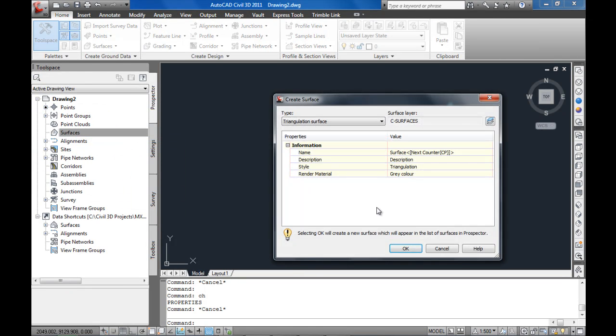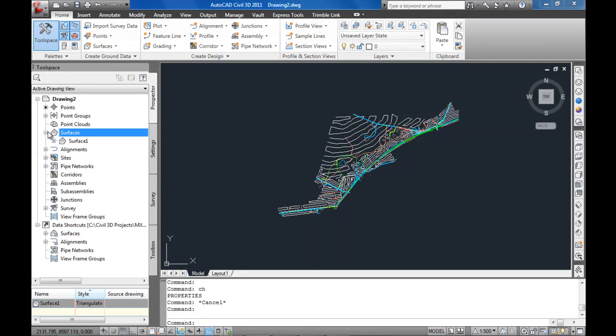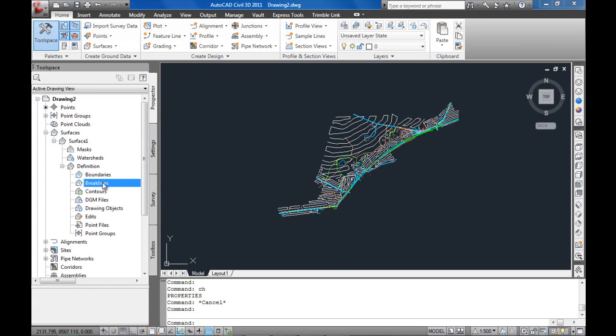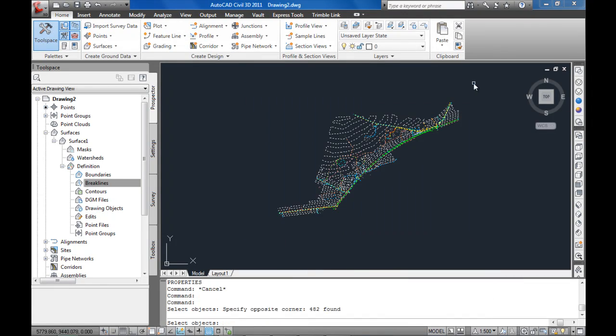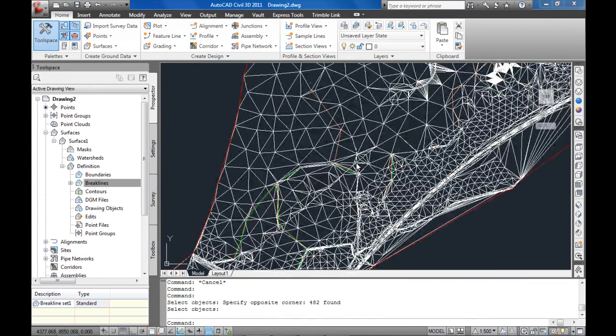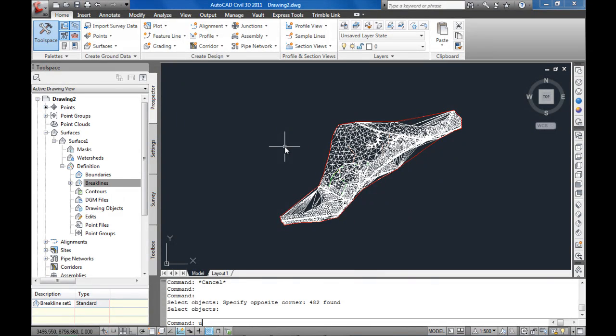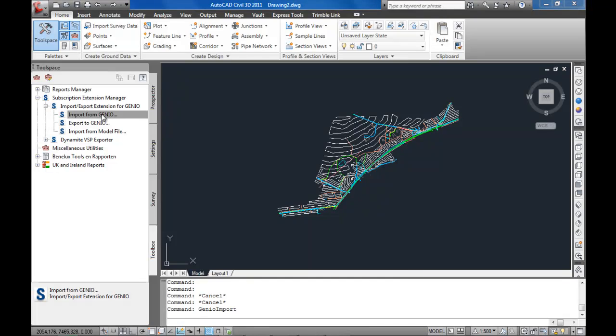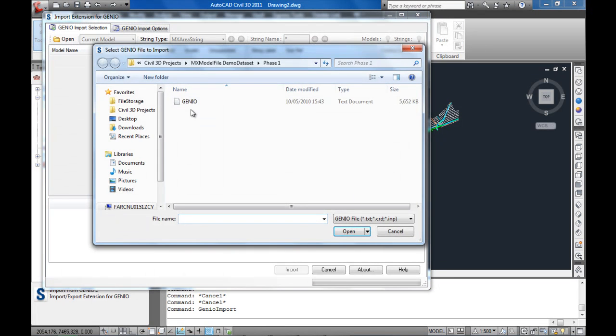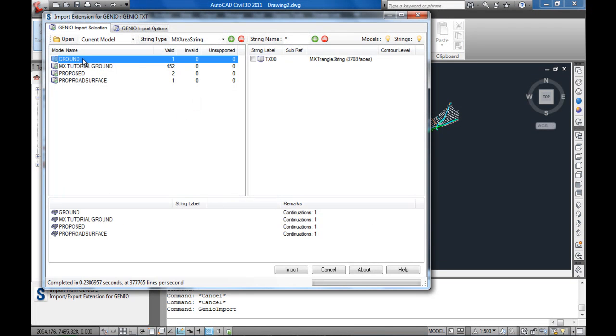Anyway, this is something now that you could create a surface from in Civil 3D, just using the typical surface creation of using break lines and COGO points if you have those within the drawing. If we step this back, we'll just undo, as if we look back in that file, you'll see there actually is a ground surface.